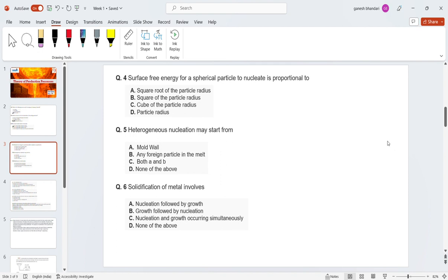Some impurities are inherent in some elements. Bismuth is the major impurity which comes in the solders, but it is a very small trace amount. That's why it doesn't create much difference in the solidification behavior. But if copper comes into the solidification behavior of lead and tin, then it will be a big blunder. Firstly, the intermetallics are majorly brittle in nature, so your soldering strength will change drastically.